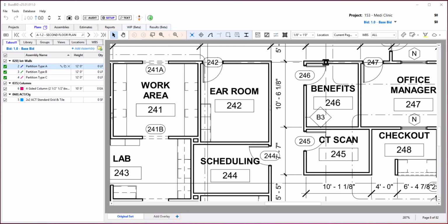The computer vision toolbar is located here in blue. The first icon turns on and off computer vision completely, so if it's off, you're in full manual takeoff mode. There's also additional computer vision tools for locating walls by wall tags, finding doors by shapes, counting corners for trims, finding shapes and shapes with text inside of them, and last, for finding and counting steel members.